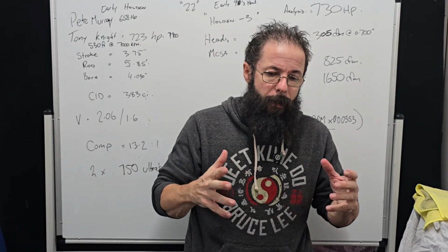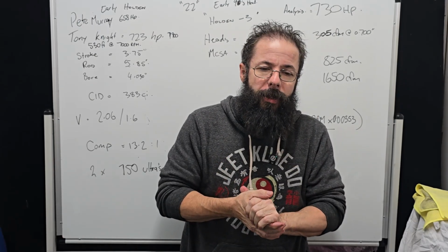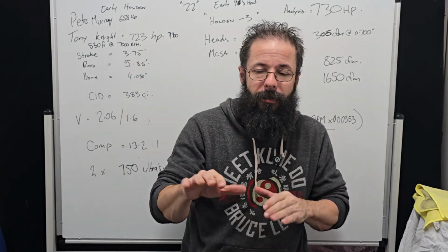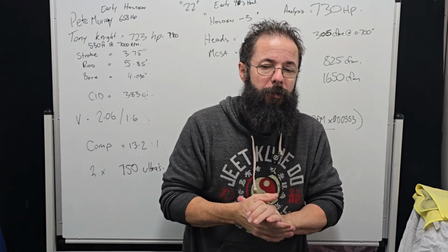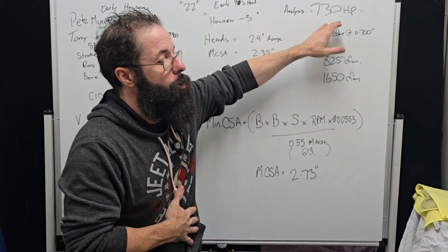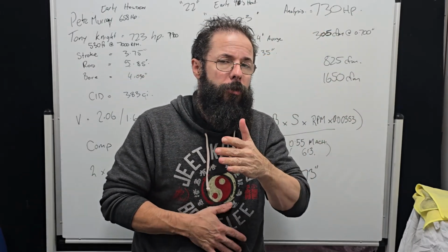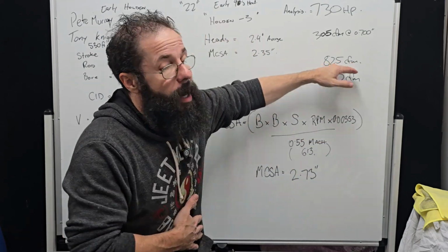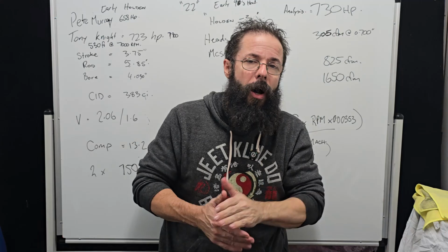And also I might demo, because we also talked about carburetor size, because Tony thinks this engine will make 750 plus. And when I originally did the analysis, we came in at 730 horsepower. So pretty close to the results Tony got. But my recommendation was twin 825s.